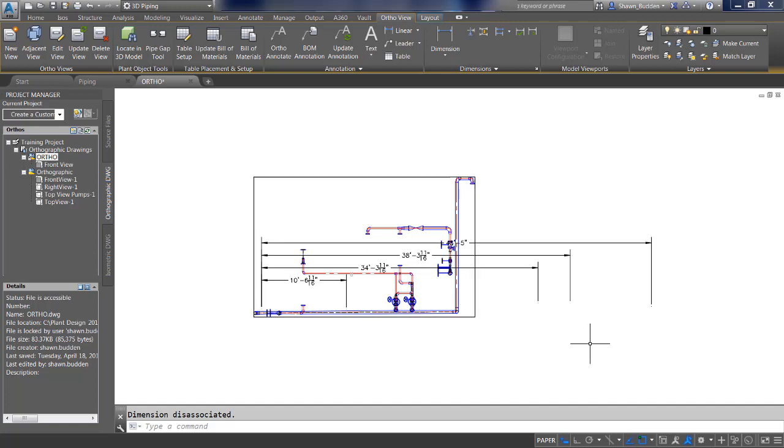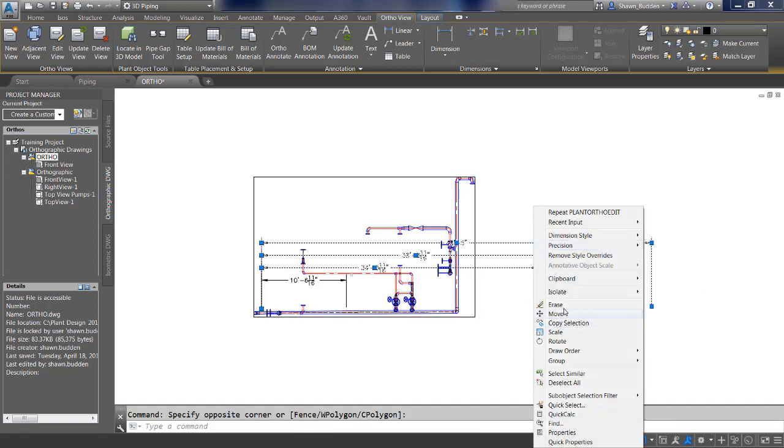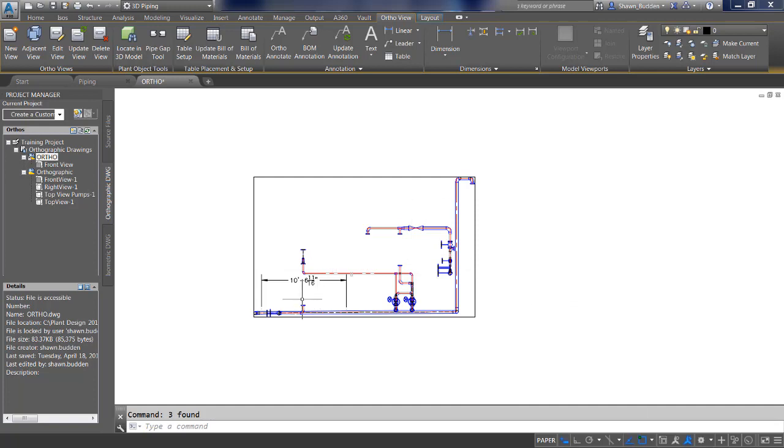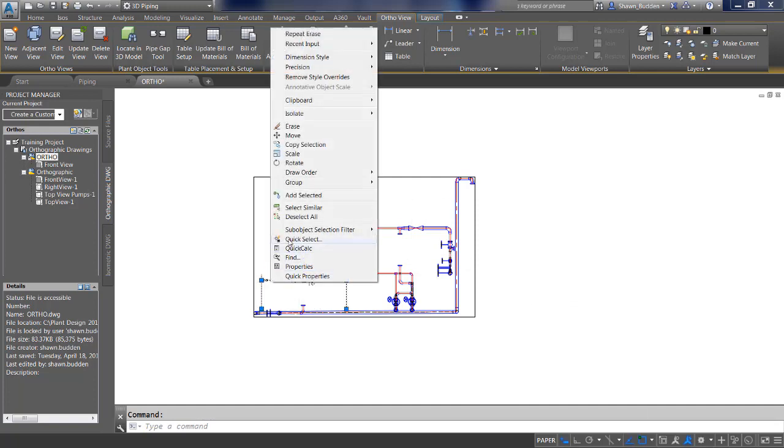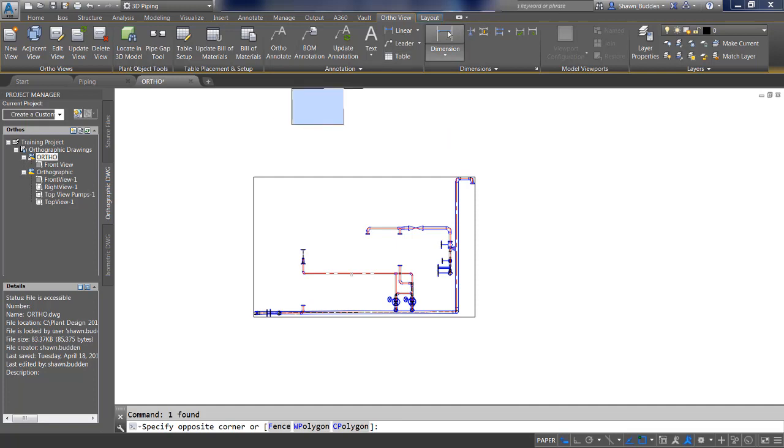So you can take them out and then just redo the dimensioning process, much the same way that we did before, whether you want to choose it by object or by picking the endpoints. But just don't forget, if you change anything in the orthographic drawing, you will have to go back and redo the dimensions manually. And that is why it is really recommended to do your dimensions as the very last step, when you will be doing no more editing.